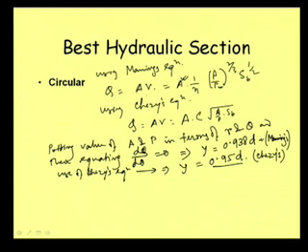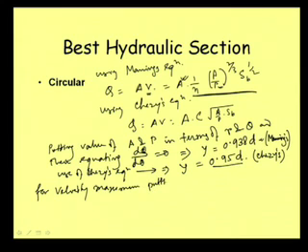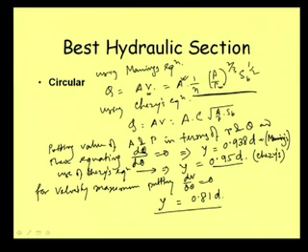But then again, V can also be expressed in this form. Putting dV/dθ equal to 0 for velocity maximum, if we do that, then we get that y is equal to 0.81 d. And that is important, by using both the equations. This is just slightly different, but it is around 0.8 d that we can see.